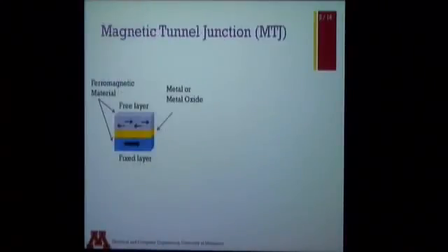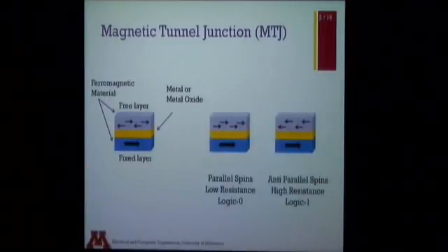So that brings us to these interesting device structures called the magnetic tunnel junctions, which, as we heard yesterday, and most of you would be familiar with, have these two different resistance states. The logic 0, which is a low resistance, and a logic 1, where the free layer and the fixed layer are magnetized in certain directions relative to each other.